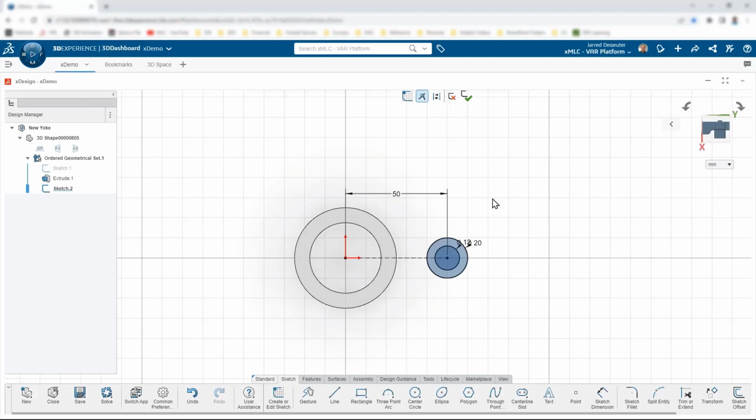There's also built-in shortcuts. So once again, I'm going to reference that line command again, just because it's really commonly used. So if I hit my L key, it brings me directly into that line command. And then I can come in and drop in whatever else I need, right? Sketch relations, also really familiar here. You can hold down Control, select multiple entities, and that flyout or context toolbar pops up, and you can jam in whatever you need. So really, really familiar, and I'm trying to kind of build that in here. That's just really familiar kind of stuff for those of you who've been SolidWorks users.